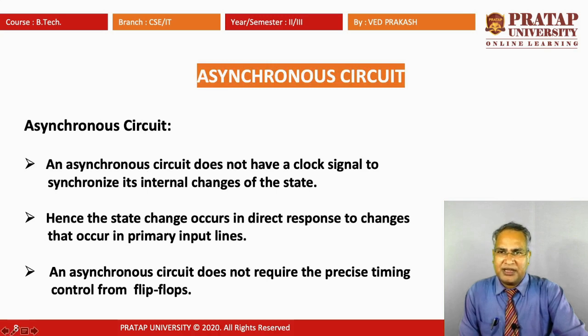Next is the asynchronous circuit. Asynchronous circuits do not have clock signals to synchronize their internal changes of state. Hence, we can say the state change occurs in direct response to the change that occurs in primary input lines. An asynchronous circuit does not require the precise timing control from flip-flops.